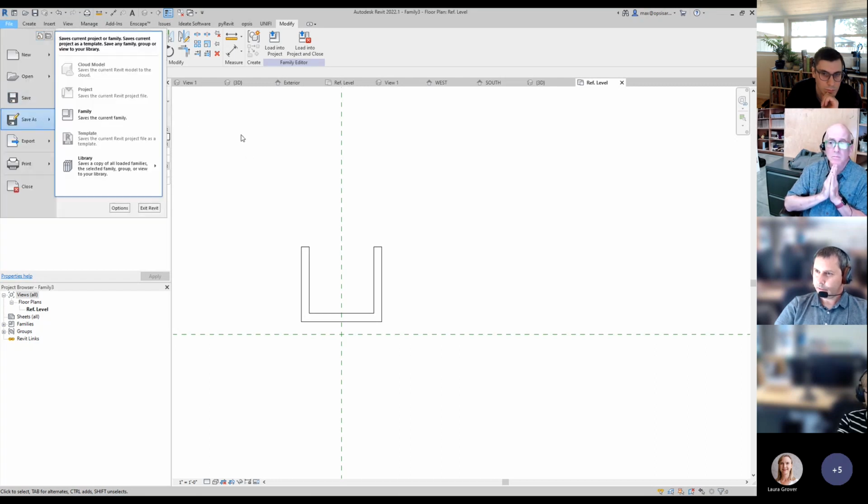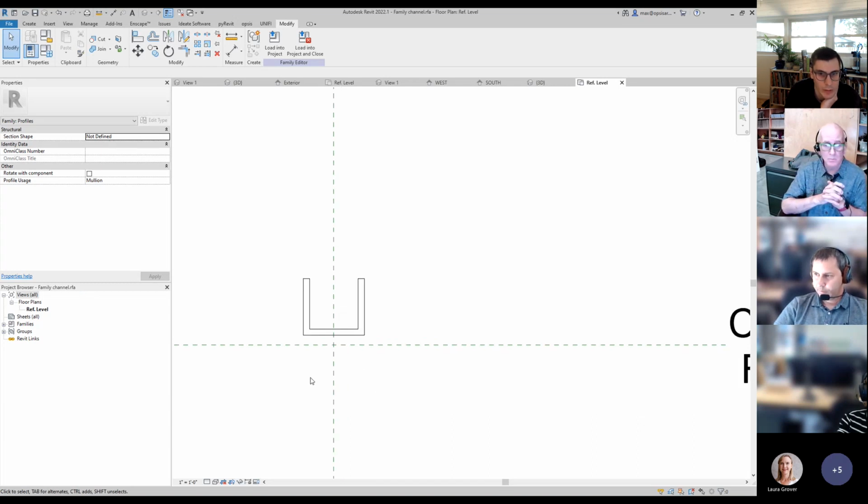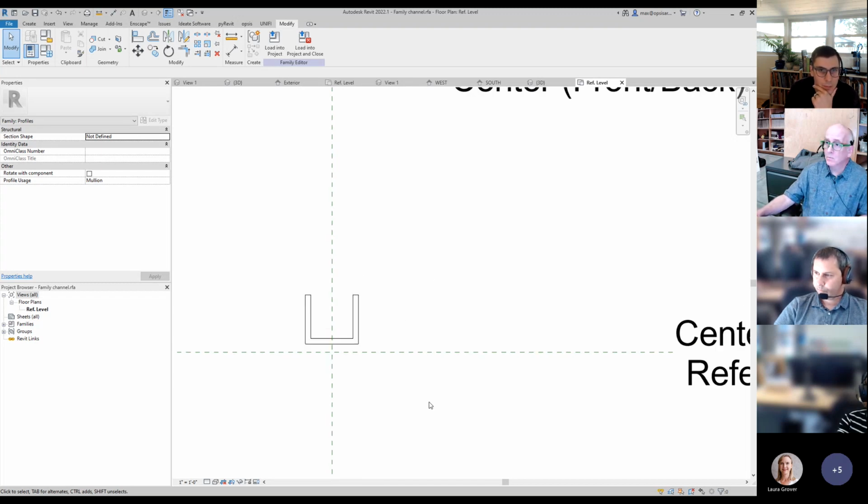So I'm going to save this real quick. And this goes back to your example too, Max, about having the panel overlap. So if you do want part of it to trim to that mullion, you can still have the rest of it extend beyond. Like the PRCA curtain wall, the wood part of the mullion extended beyond so it could sit behind the snap cap. Right.